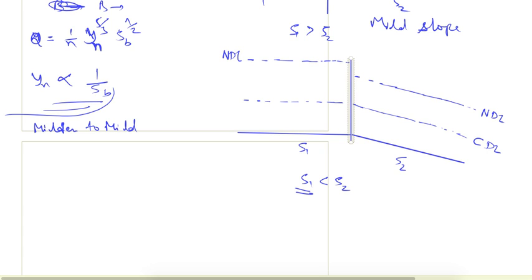This is again our control section. As I said, the control section is the downstream in case of subcritical flow. So again both cases are downstream, but here we don't know whatever is happening in the downstream, but this is the upstream point for this case, so this will not be affected by this control section.